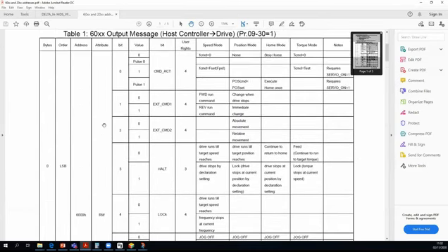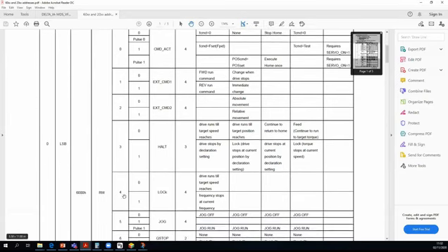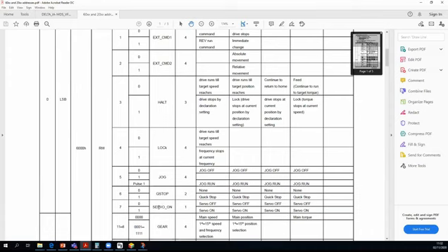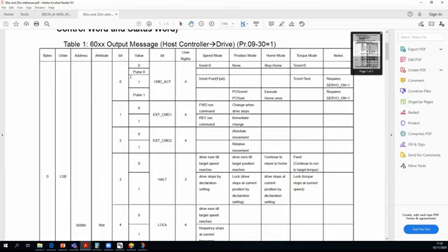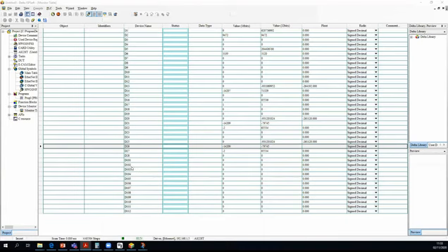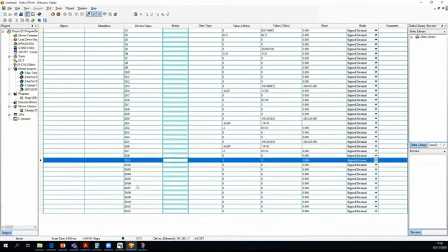So this is my definition for the status word, 6000. I can see here I have servo on bit 7. And to actually move to position, I have bit 0. So when I set bit 0, then the drive will move to whatever position I set. And I have here bit 2, which I can use to switch between absolute or relative positioning. 0 is relative and 1 is absolute. So firstly, I need to see where exactly 6000 is defined in here.